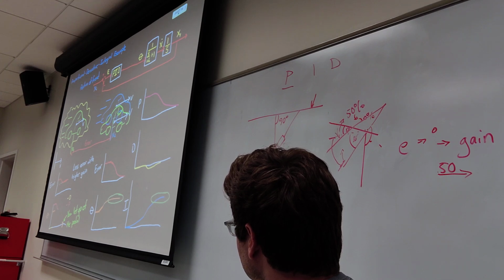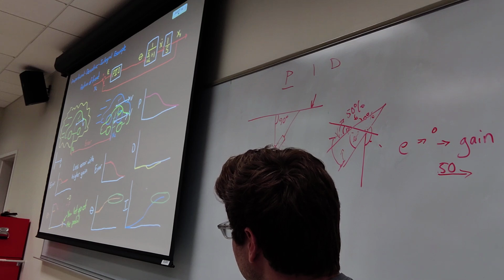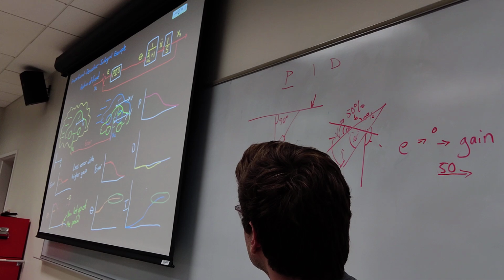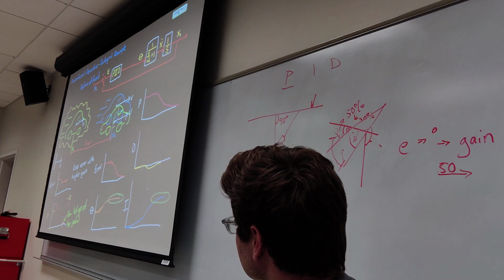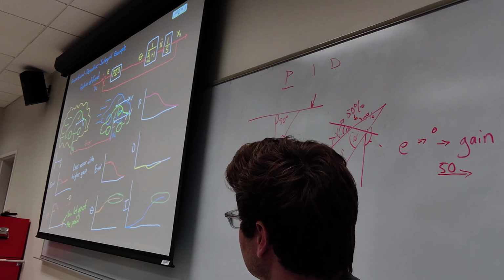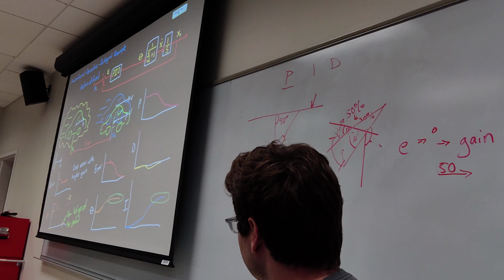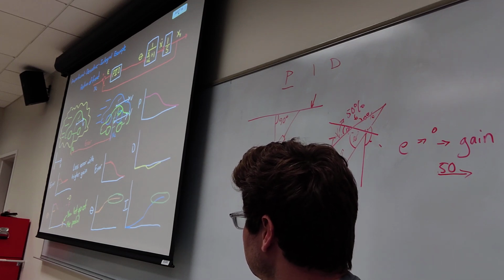And in these thought exercises, we really only looked at one of those requirements, and that is whether the error in the system eventually reached 0. However, in a real system, you tune the controller for much more than that. For example, you might be concerned with overshoot or rise time or settling time. And I'll cover how to tune PID controllers in future lectures, and we'll touch on each of those requirements and more. But for now, I hope this gave you a little bit more intuition on how each of these three paths in a PID controller contribute to the overall control system.